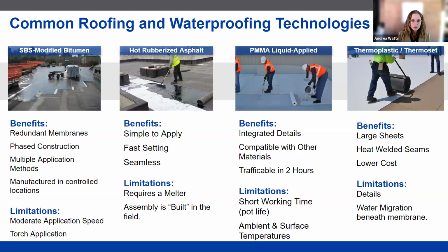They don't have a lot of seams on the roof comparatively to these other technologies, but then we seal these seams either by heat welding, if it's a thermoplastic membrane, or using some sort of tape or adhesive if we're using a thermoset membrane, to create an impenetrable lap when it's done properly. Now, these membranes as single plies don't typically allow for a lot of redundancy, especially when we come to our flashing detail configurations at our interfaces, at our drains, that are more commonly associated with the other types of membranes that we're going to talk about.